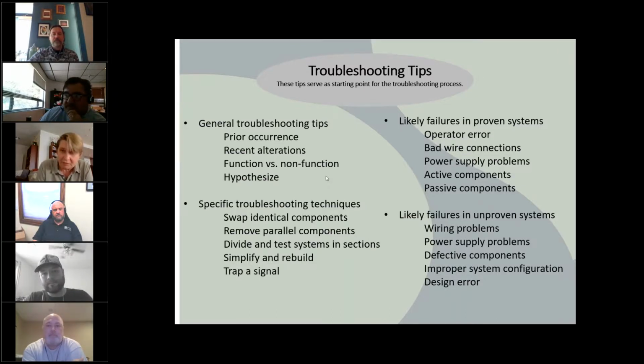Start, do you have power? Is there an issue with the breaker? Is there an issue with the outlet plug? Is it on the right kind of circuit? Starting there will get you your resolution faster than just jumping ahead to something. Because what oftentimes happens with jumping ahead is you start to replace parts that don't work. You replace more parts, that doesn't work. The machine's down longer. The customer's frustrated, you're frustrated, and you've spent a lot of money that didn't need to be spent.